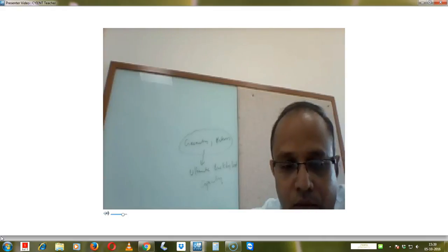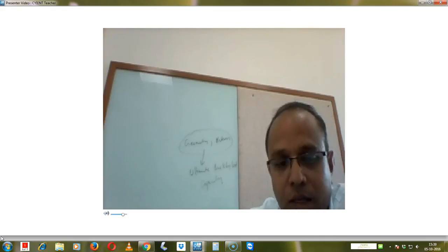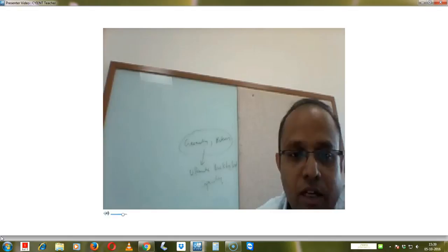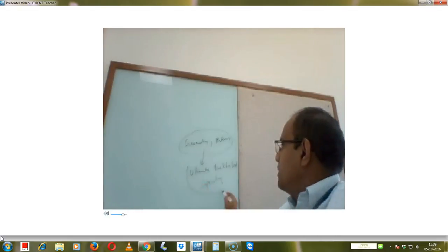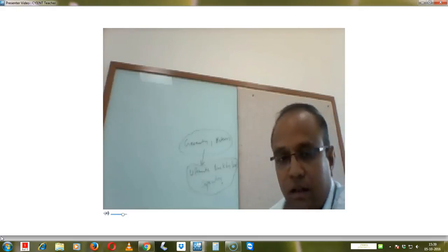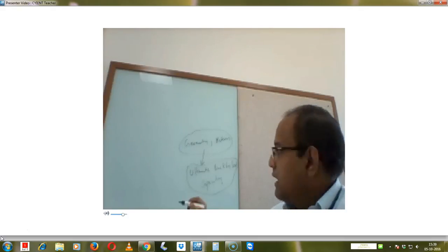So buckling analysis is basically done in order to evaluate the ultimate buckling load capacity of the geometry. Then we need to check the margin against the applied load.